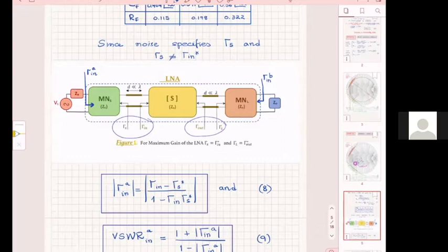Because these matching networks need to create an appropriate reflection so that the transistor, with those reflections and the input port and the output port, creates the right amplifier. Without those appropriate reflections there, this transistor is not going to operate. So by introducing this matching network at the front and the matching network at the back, the green and the pink, we are introducing these additional parameters that do a number of things for us.